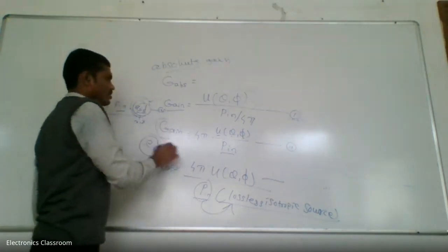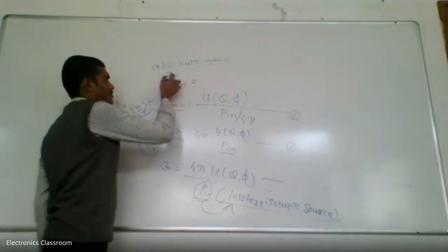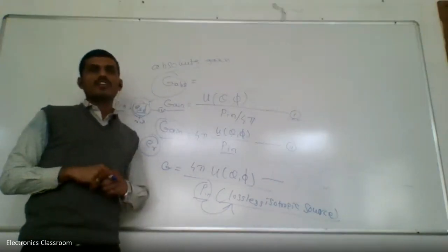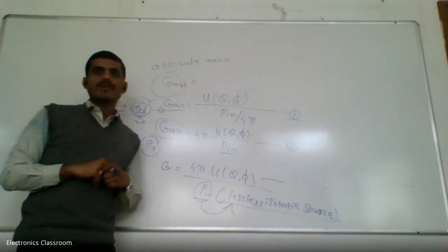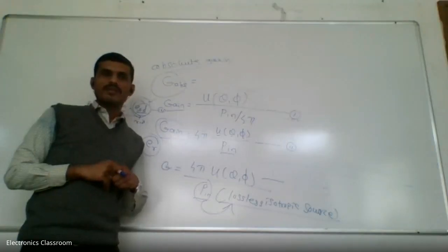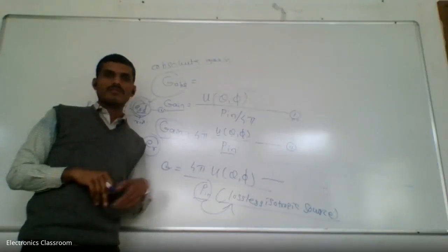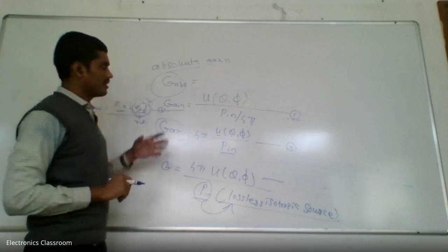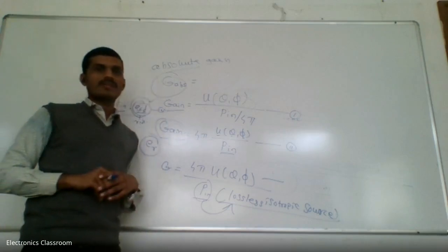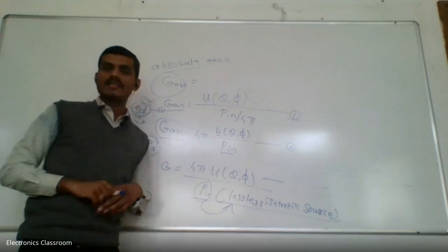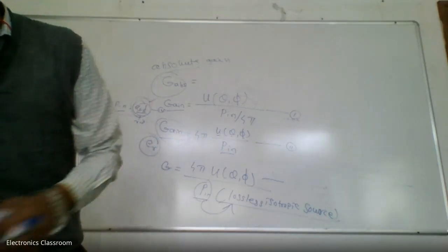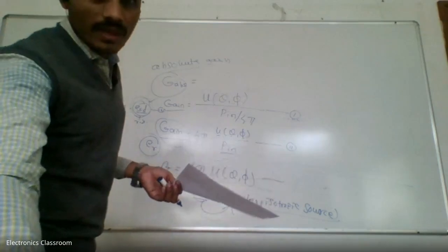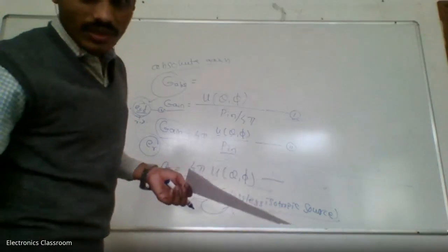If the gain does not consider these losses, it will be considered in your absolute gain. That means your reflection and polarization mismatch losses can be taken into that particular equation, and we can write an equation for that gain. This can be rewritten.